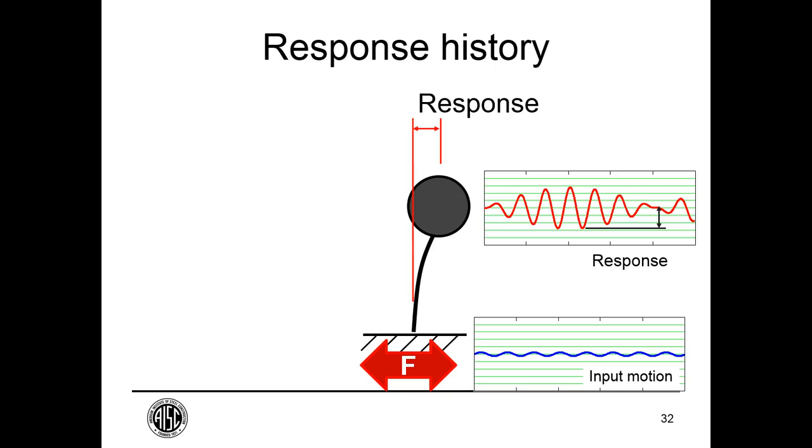And we estimate what that response is as a function of that input motion. So far, it's fairly simple. That response, again, could be anything that we think is significant for design. We might use displacement to monitor and limit it to a code acceptable displacement. We might use shear and overturning to quantify what we need to design different elements for in our lateral system.